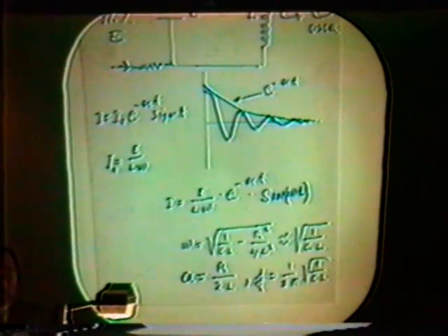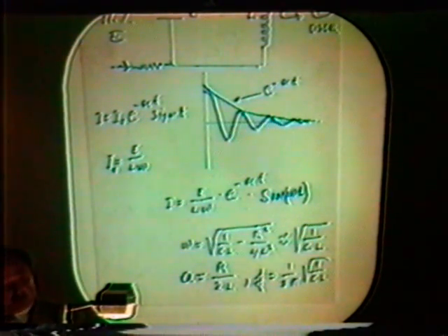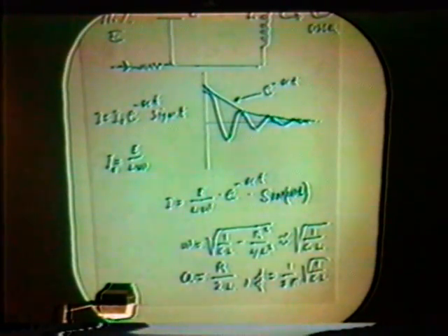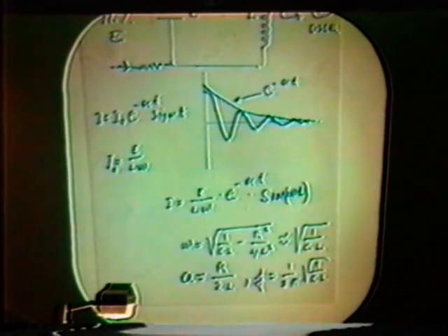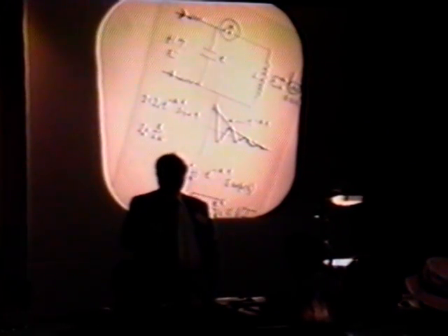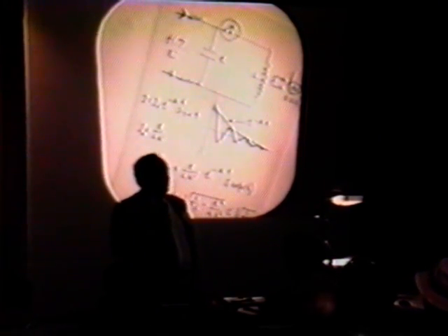The frequency depends on the capacitance and inductance in the circuit, in the usual manner as everybody knows, and the damping factor depends on the resistance and the inductance in the circuit. Okay, this is clear and straightforward for such circuits. Actually, what we assume happens in a spark is that an avalanche starts, and the resistance of the air breaks down, dropping practically to zero. That's what theory says. Now, I will show you some oscillograms from various cases concerning this effect.